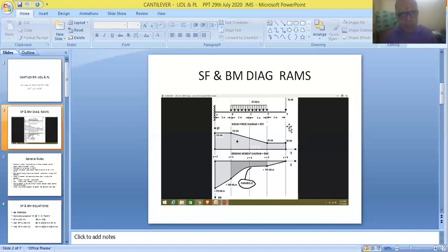So friends, finally, we have to start doing the problem. We have to start from the free end of the beam, proceed in reverse direction, and finally reach the fixed end of the beam. So this is the way of doing the problem. We don't need 4 portions; 3 portions are sufficient.